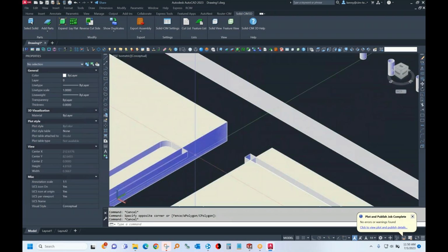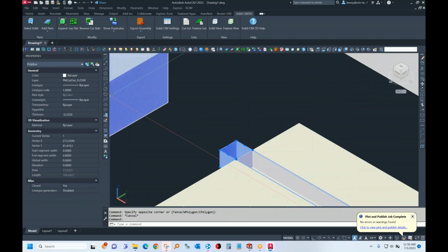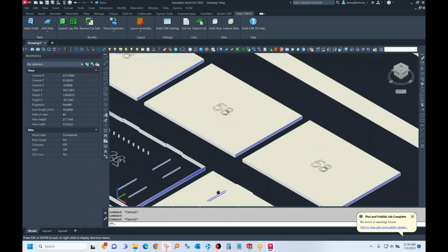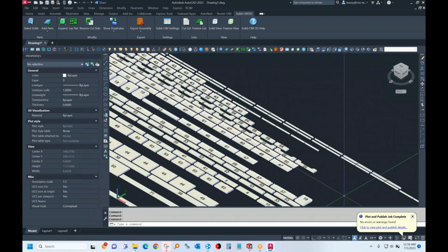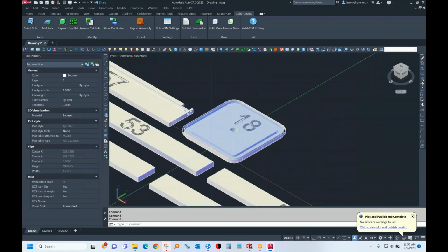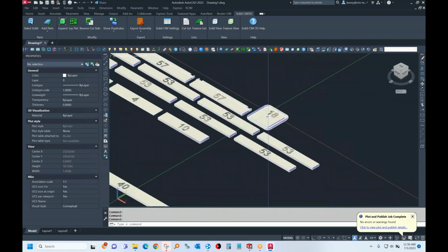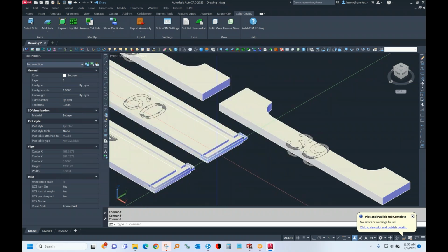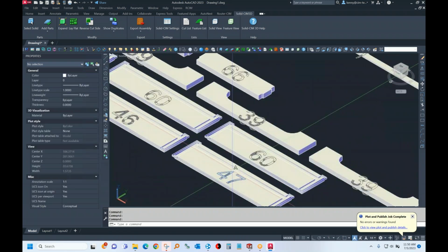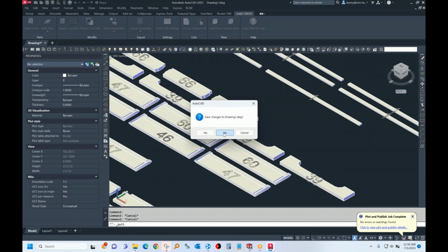Notice, too, that the dados and the pockets are extended past the edge of the part so that it'll cut all the way out. There's a pocket cut. All of these features are recognized, and you get automatic feature recognition. You could also turn things off here as well. So this little part here is going to pocket in between these two edges. It makes a layer pocket. There's some pocketing going on here and some drill holes. There you can see some extension past the edge of the part for that pocketing, and the part numbers are on there too. So that's the lay flat feature. You don't have to do that, but it's just very neat to be able to do that.